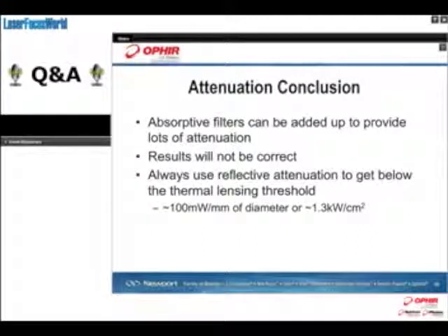With a scanning slit profiler, you do have the advantage of knowing exactly where your measurement plane is, and that is where the slit is going through the beam. So people often ask, where's the detector? That doesn't matter. The detector's behind the slit, but the measurement is made at the slit. And you know that position, certainly within